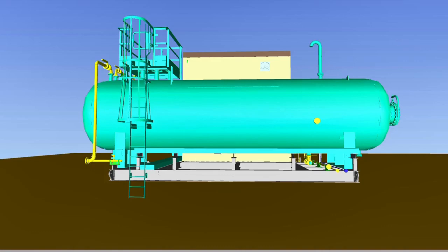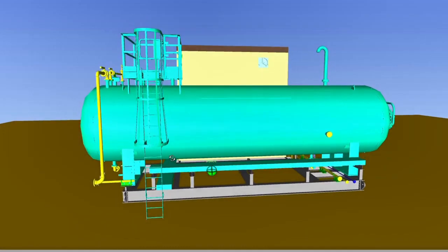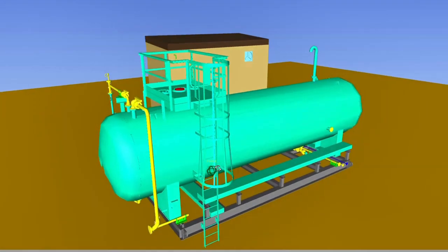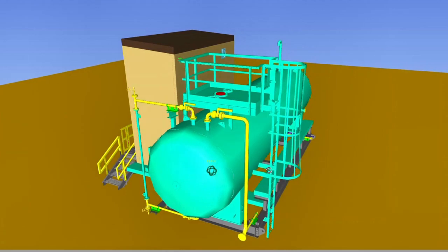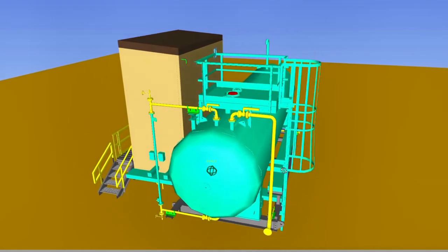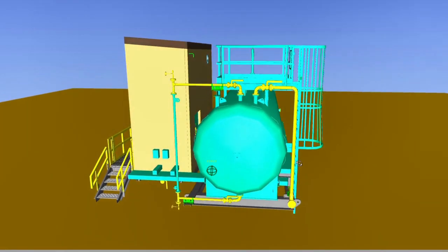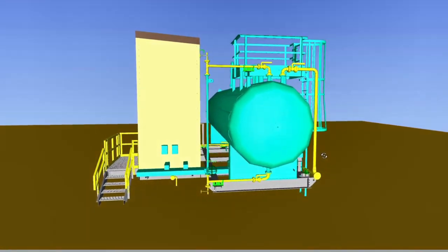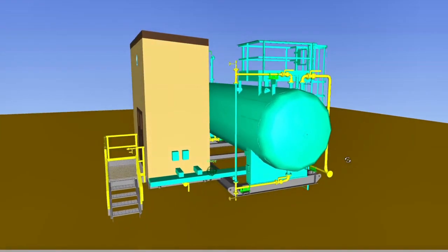Welcome to example 6. In this example, we will classify a process vessel handling crude oil. Crude oil is a mixture of hydrocarbons that exists in the liquid state at ambient conditions. Of all the components in this assembly, the most likely source of release would be a flange connection or open-ended device that would result in a pool of crude oil collecting at grade level.